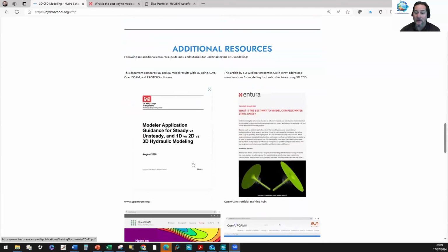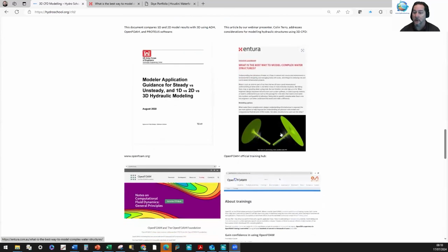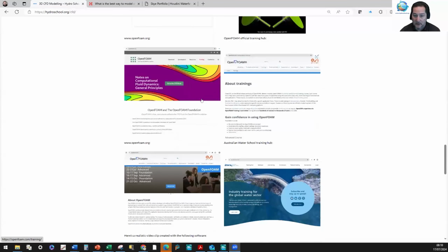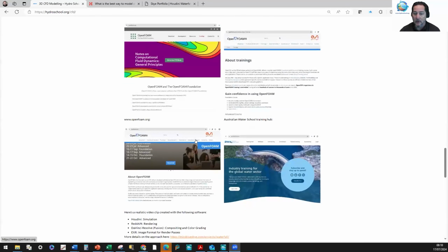There are some additional resources that I'll show you here as well for anything you want more information on. There is a comparison between OpenFOAM applications and some other 3D CFD applications versus HEC-RAS examples in 1D and 2D in this document that's available for you to download. And our expert presenter today, Colin Terry, has written this article on Entura's website, which talks about the pros and cons of approaching hydraulic structures with different models. We will talk a little bit about the difference between openfoam.org and openfoam.com, including the training page that they've got here.